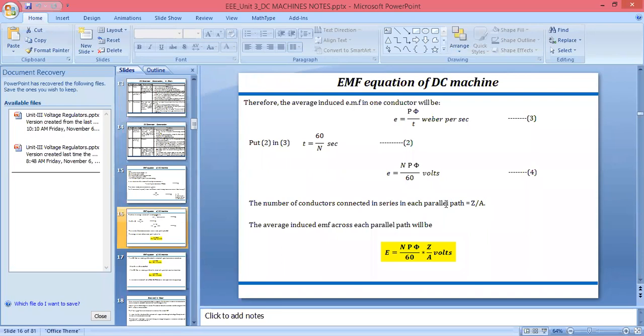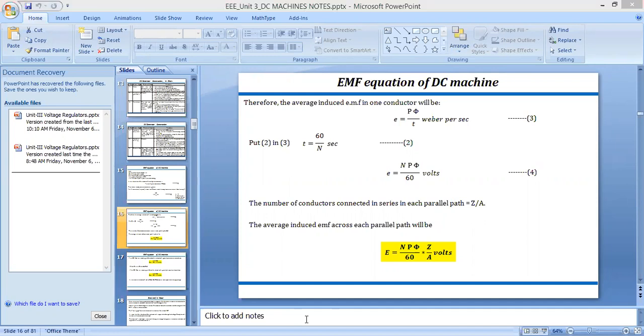Again, if you put the second finger of your right hand, it will be perpendicular to the first finger of the right hand. At that time, Fleming right hand rule states that if you put your right hand with your thumb and two fingers perpendicular to each other, your thumb will indicate the direction of motion of the conductor, and here, instead of a conductor, we are taking the armature as a conductor.